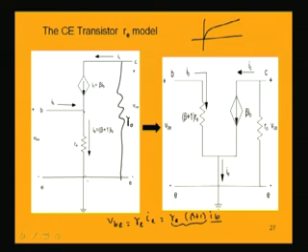This circuit and this circuit are not different, these are the same circuits, there is no ambiguity or any confusion between these two circuits, only conveniently it is drawn like this just for easy analysis, and actually the resistance RE is now reflected as (beta plus 1) RE, but you see the current, this is the base current, is the same current flowing in the resistance as well as the starting or the input current. So, this current IB is flowing through this resistance, meeting here with the current which is from the collector, this is beta times IB. So, IC plus this IB is now IE which is flowing to the ground.